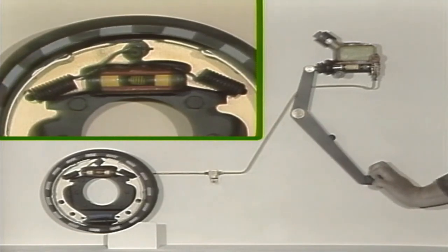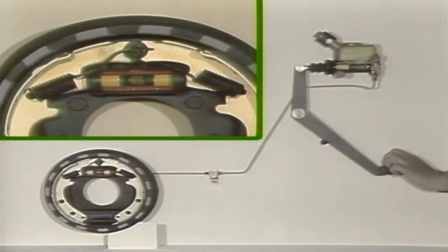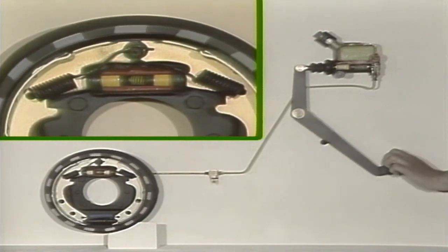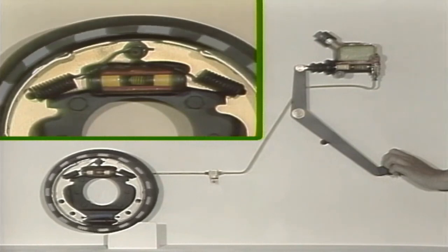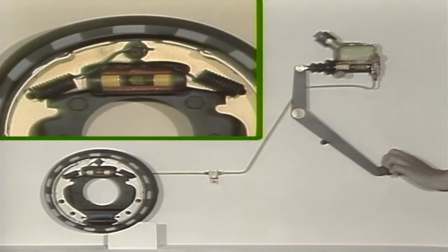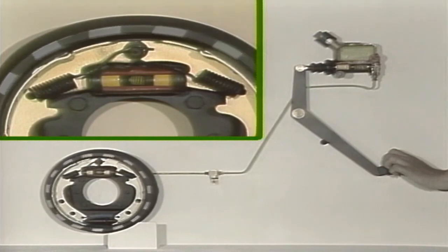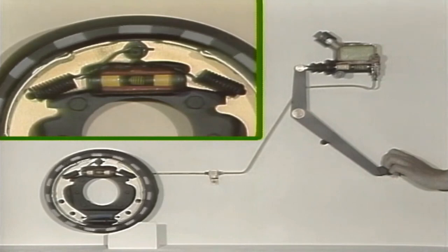Releasing the brake pedal lets the return springs pull the brake shoes back from contact with the drum and drive the pistons back to their stops in the wheel cylinder. The master cylinder piston driven back to its stop allows pressure in the system to decrease, but the residual pressure valve closes, keeping just enough pressure in the brake line and wheel cylinder to keep its sealing cups pressed against the pistons. These face inward so no brake fluid can escape from the system.